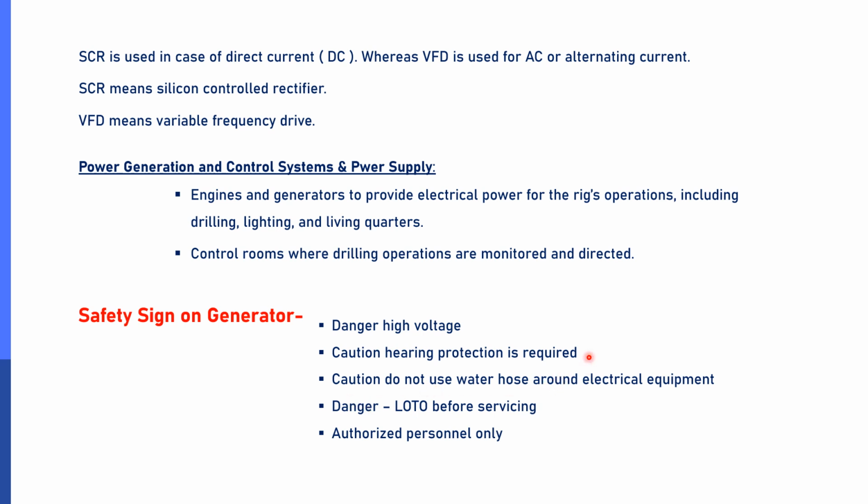And here one more thing I want to share: there should be safety signage mentioning the caution, hearing protection is required, and the safety officer has to ensure that some extra fresh, unused, new earplugs have been kept in a box over there, which should be protected from sand or other chemicals, so that they are fresh and usable. If anybody comes here for any work, due to the noise of more than 85 decibels, he can take the earplugs from there and use them.